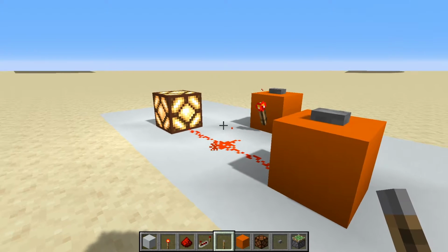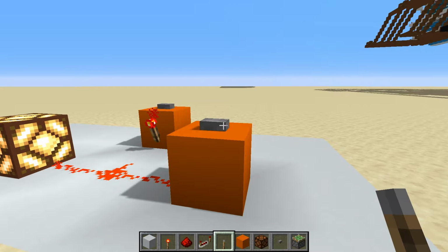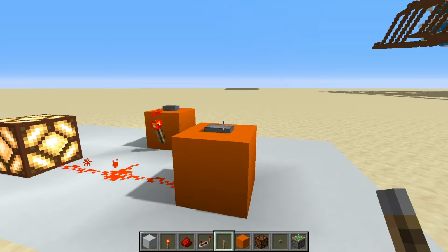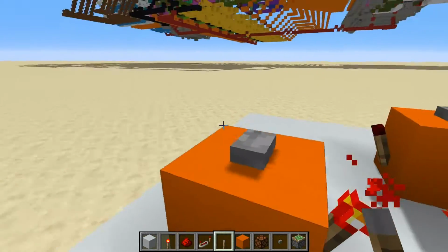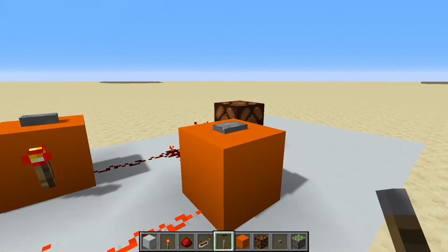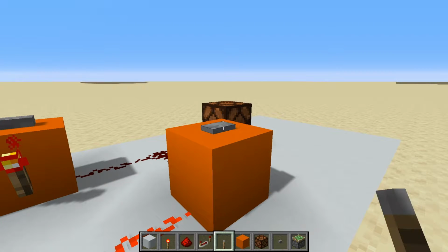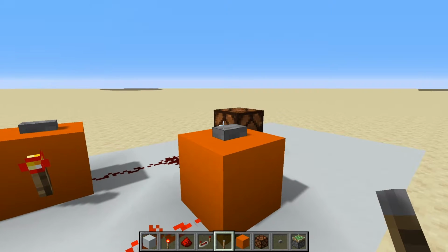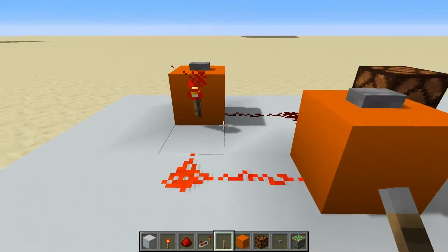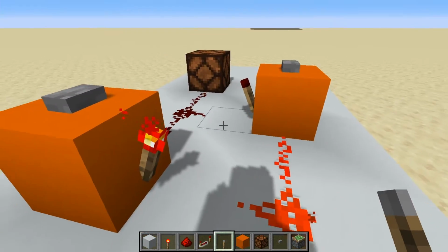I can turn it on, and it holds the value after the button's been unpressed. And I can keep pressing it, and it doesn't matter. If I come over here to the reset button, that turns off the lamp. And again, pressing it over and over does not change the state. So that's what I mean by memory, and this entire configuration here is called an RS NOR latch.